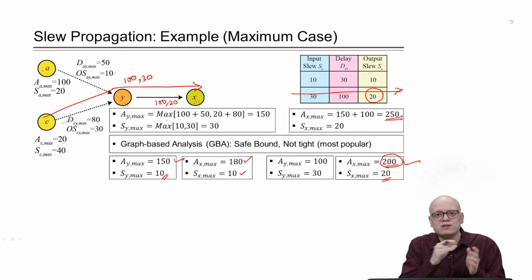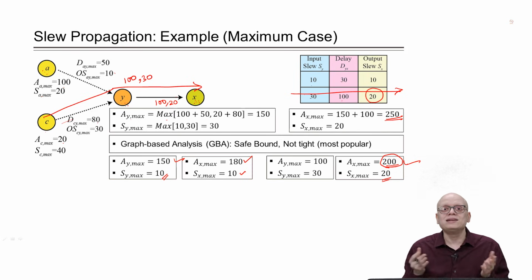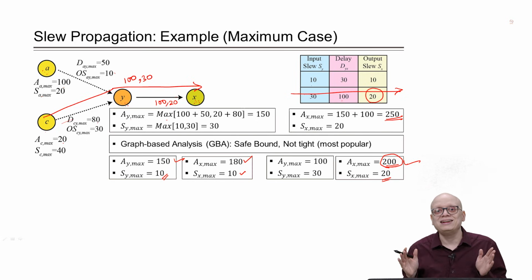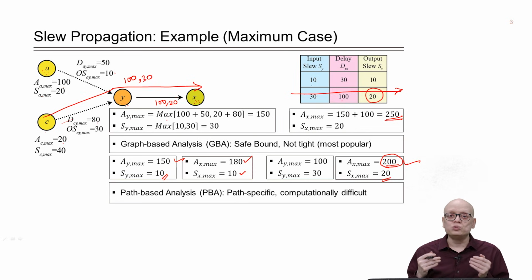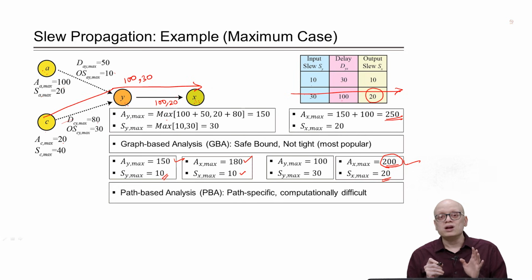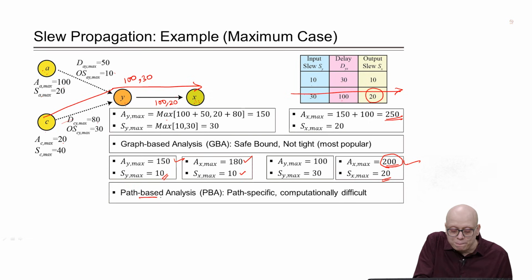This is just an example here, only two paths were involved, but in realistic designs there will be lots of paths. So, we cannot exhaustively do the timing analysis pathwise, because there are too many paths in our circuit. So, what commercial STA tools typically do is that they provide some mechanism to carry out path based analysis also. This is known as path based analysis or PBA.